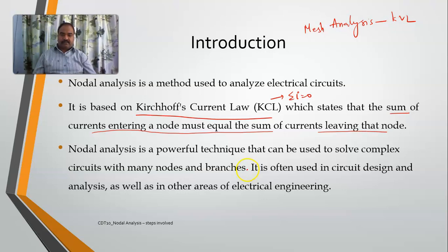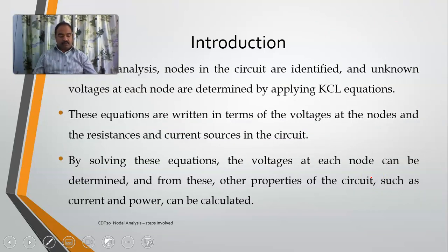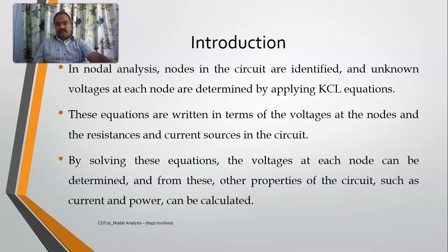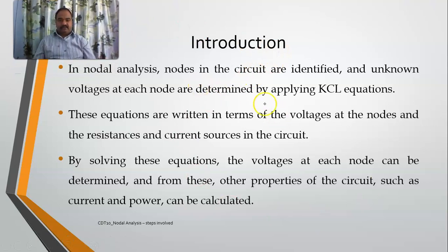Nodal analysis is a powerful technique generally employed besides mesh analysis. Normally in electrical circuits, we employ it to determine the branch currents, branch voltages and node voltages. In this method, first of all we identify the nodes in the circuit, and then we assign them some voltages. And then we determine those voltages using KCL equations.